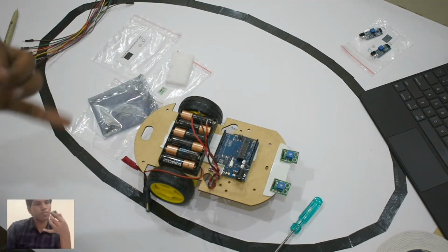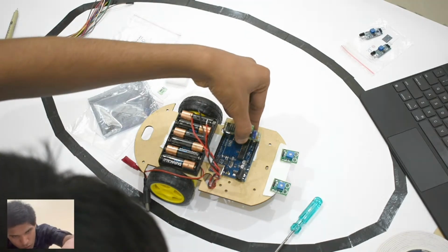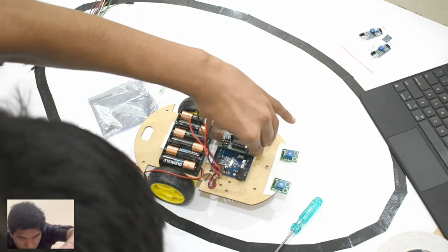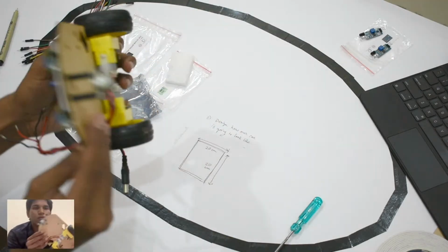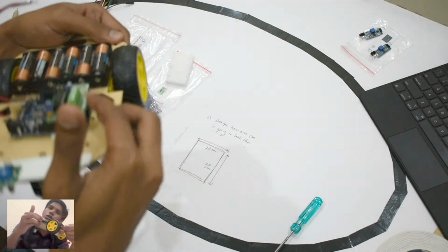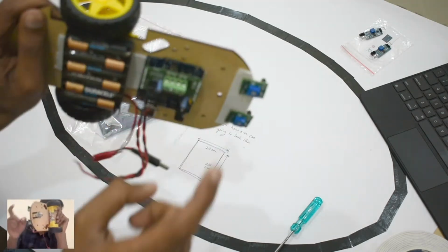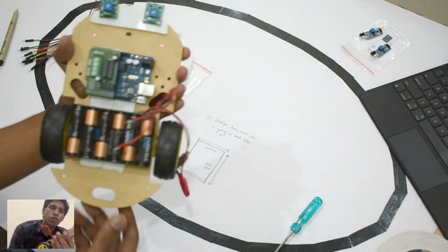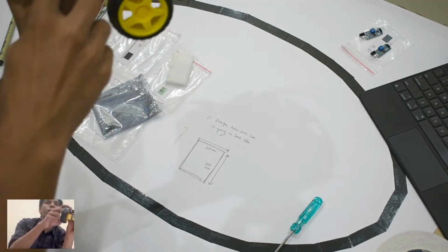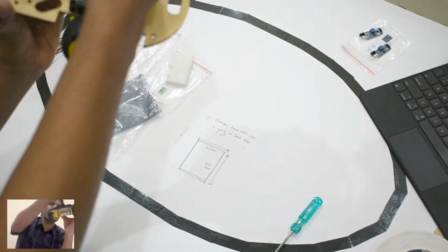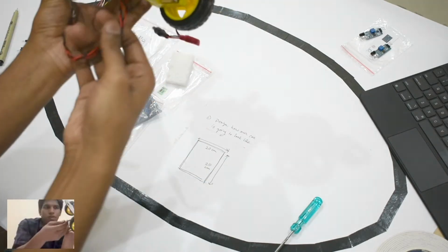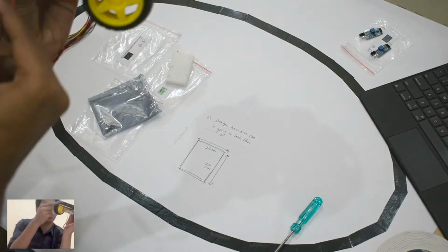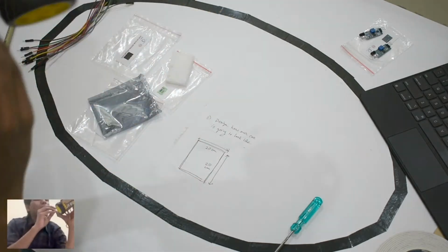So it's going to go like this, and it's going to fit here. So you can see the motor driver is connected to the Arduino. Okay. Good. So now you will notice that the motor shield has these four pins here where I can attach my motor wires. Okay. So I'm just going to bring out the wires from here. The slots are here. So I'm just going to bring out these wires and connect them one by one.